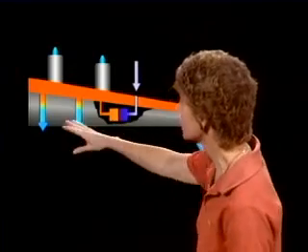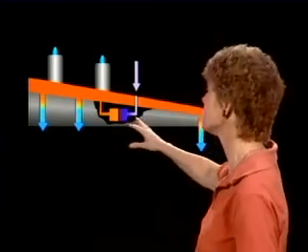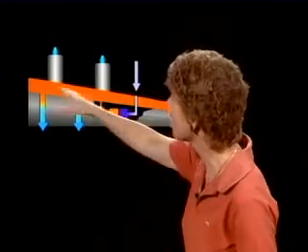Combustion heaters in aircraft can range all the way from a small nose-mounted unit to heat the cabin of a small twin-engine aircraft, or they can be combustion heaters in large piston-engine aircraft that not only heat the cabin but also provide hot air to heat the leading edge of the wing.